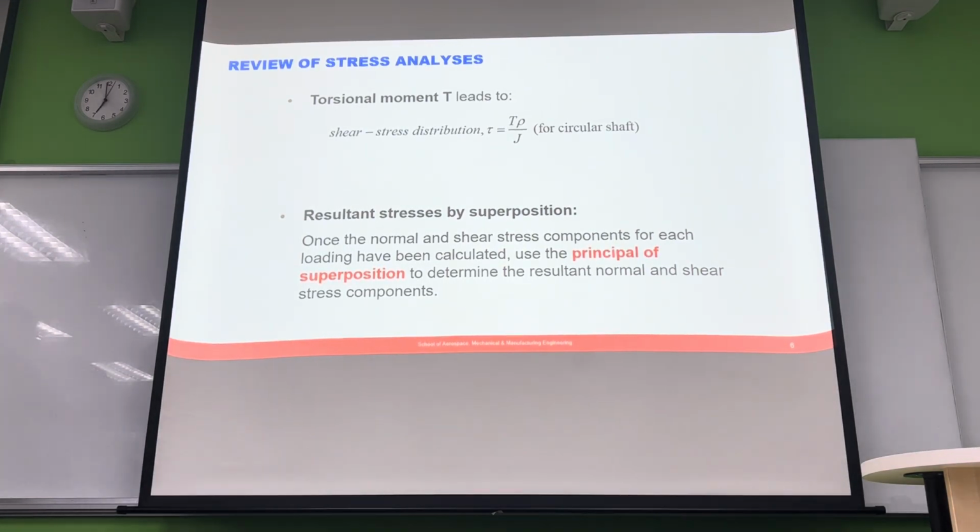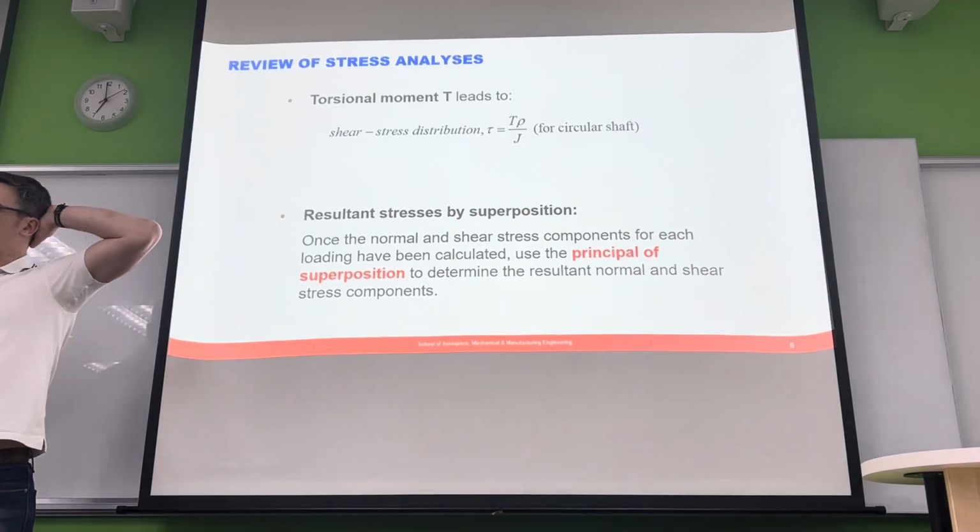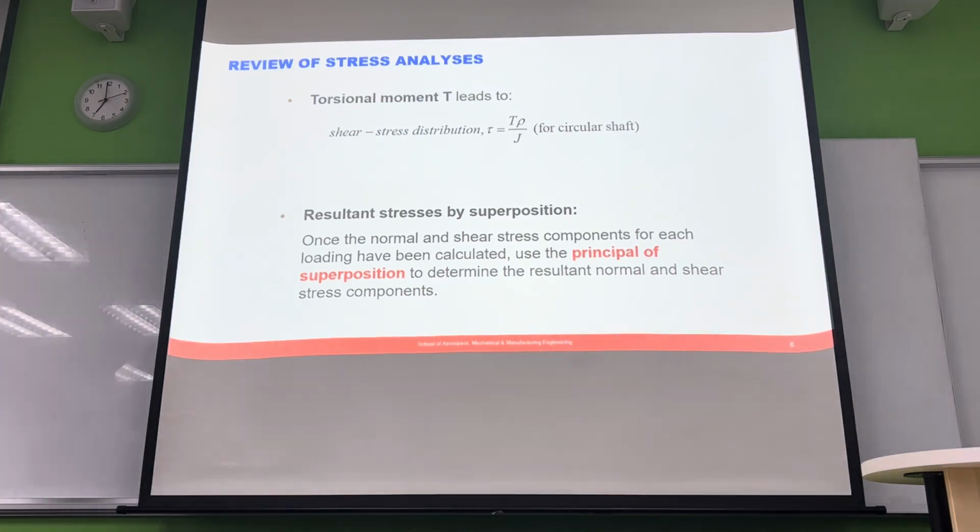It doesn't have discrete sections. So one of the key things about stress analysis in continuum mechanics, and particularly for linear analyses, is the principle of superposition. What that means is if I have a vector in a particular direction and another vector at that same point in the same direction, you can just add them together.